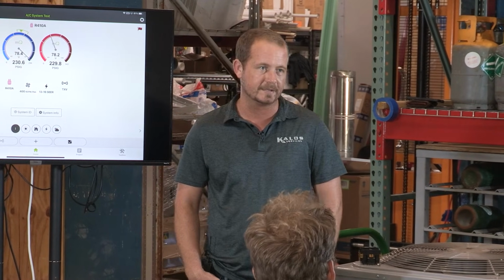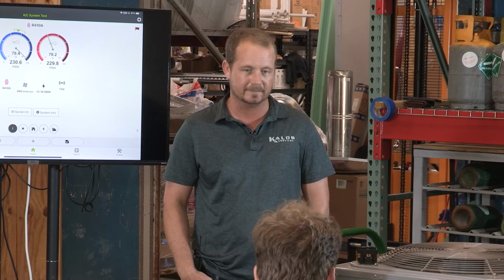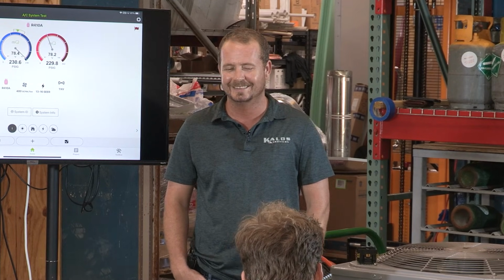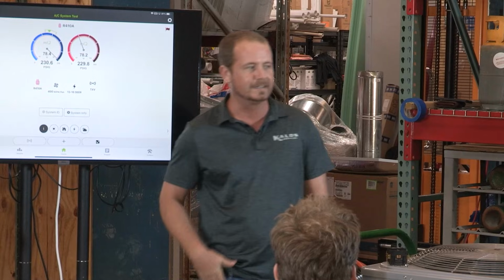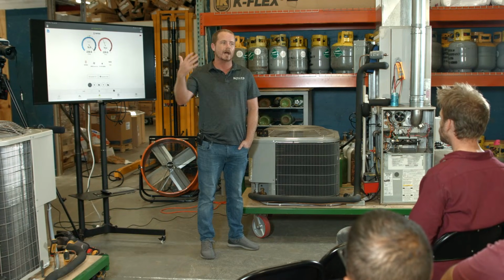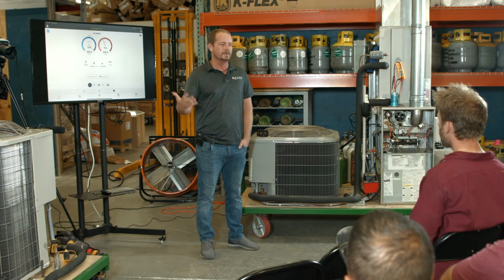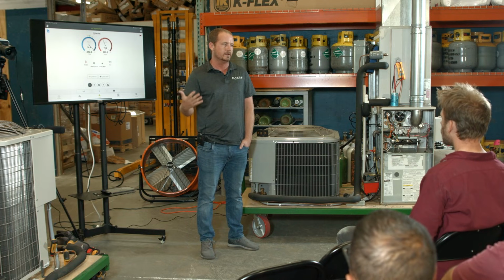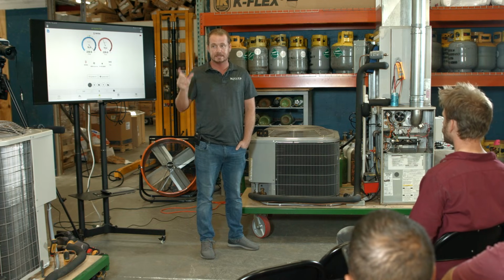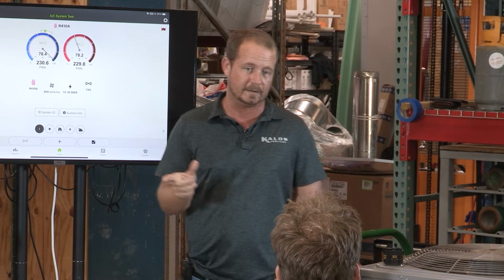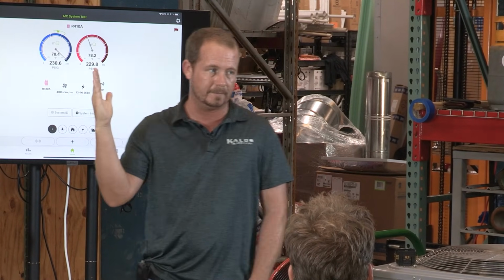It's like a husband on the weekends. It does nothing. True. So all it does is reduce its output. It does not ramp up, and so it doesn't try to compensate. There's no compensation taking place, so it won't be noisier because of high static pressure. A PSC will not be noisier because of high static pressure because it's not attempting to ramp up.